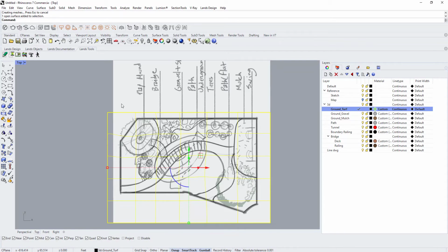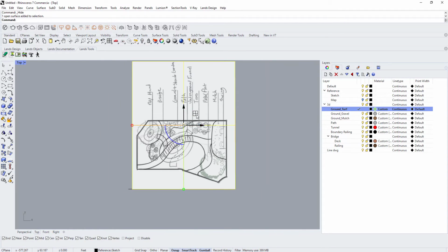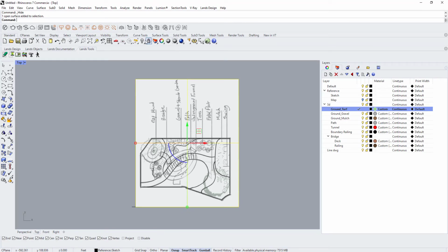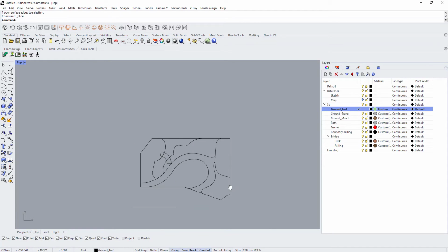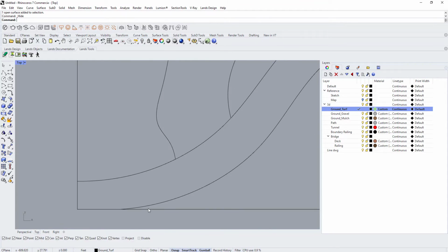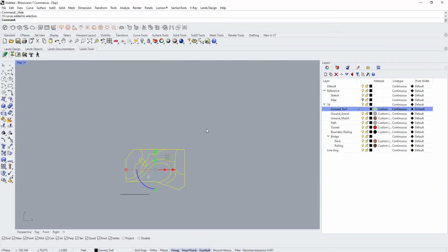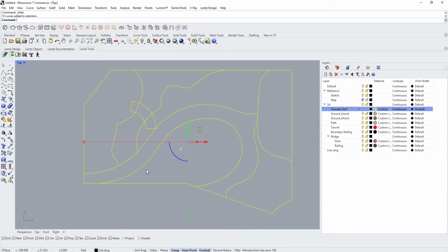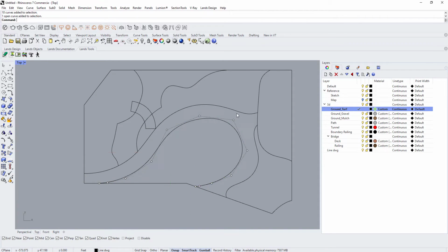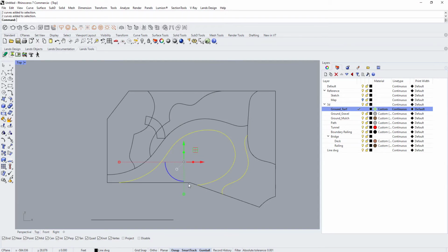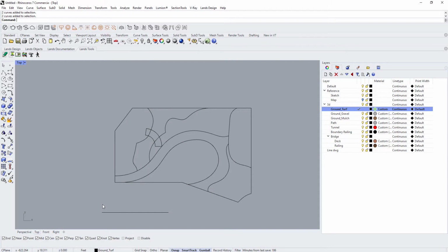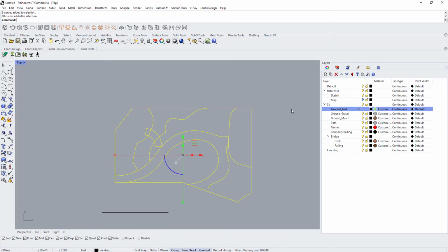So at first I will hide my ground plane and try to look at my line drawings now. So I'll hide my drawing 2 at the moment, select the line drawing like this, and try to understand where the path is. So I can see that this is the path right here. I have made it with an open polyline, which might be the case for some of you, but if you have done it with closed polylines, you're set to go. But there's a neat trick to set up a closed polyline on the fly.